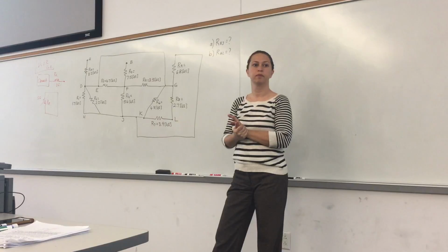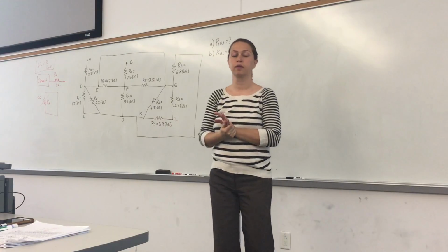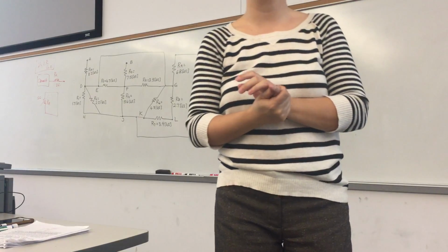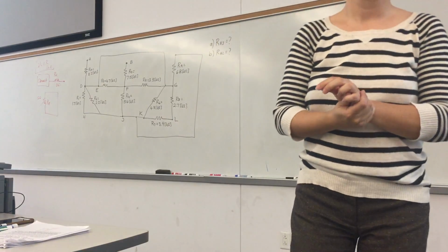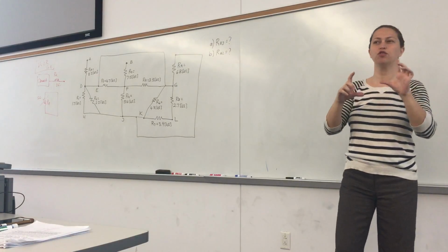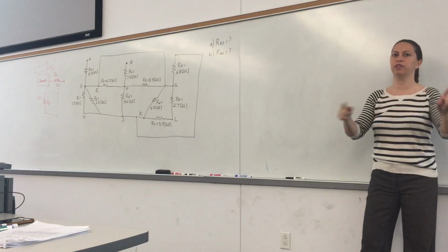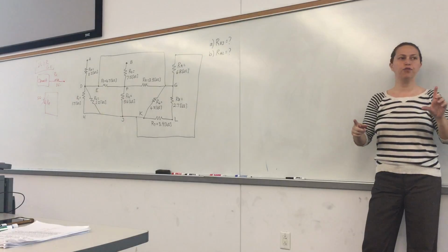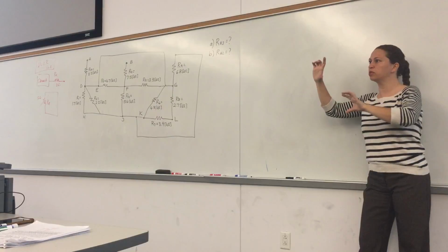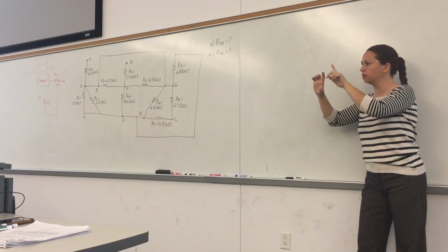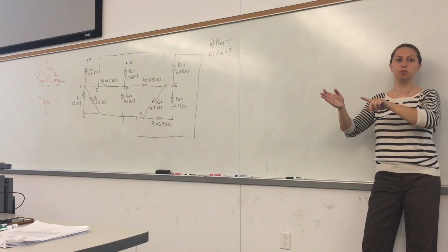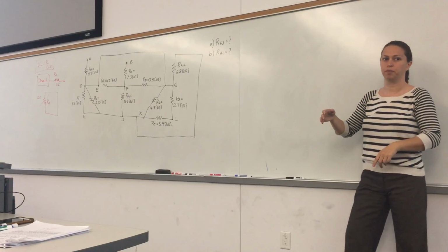You can get rid of this one right here. When you put it all together, does it end up becoming the same? You have to think about it carefully. So when a resistor is shorted out, you have to be careful. You can't ignore everything, okay? If you are sure that you're ending up with an equivalent resistance in parallel with a wire, which is going to short that resistance, you can get rid of it, but that's not always going to be the case. We'll talk about it.